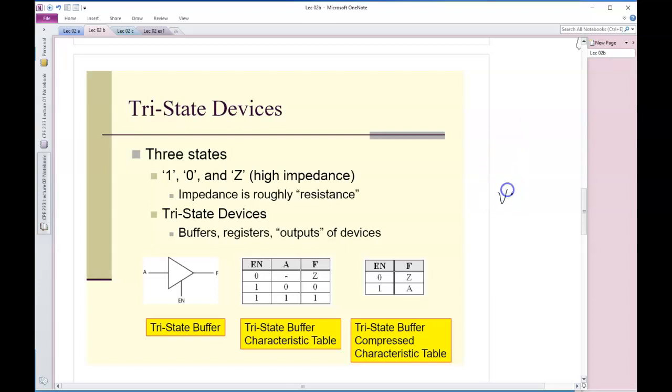So what we have is V equals IR, right? I know people have worked with resistance and impedance probably in your circuits courses. But if I switch this around, R equals V over I. High impedance, the impedance is kind of like the resistance, for lack of a better word. We'll go with that. If it's high impedance, that implies R is large. For a typical digital system, the voltage is fixed. It's not going to change. So if R is large, I is small. This works all the time. High impedance means extremely low current. Extremely low current is close to no current. No current is close to an open circuit. No current is an open circuit.